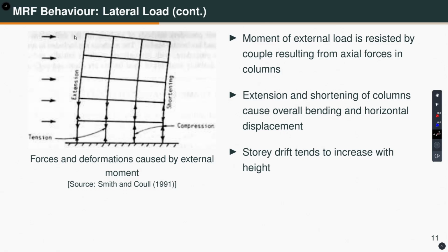Now, how is the bending moment resisted? So, we talked about you apply the lateral force, column is developing the shear force, right, and that causes double curvature bending in the column and consequently in the beams, and that double curvature bending leads to shear racking.